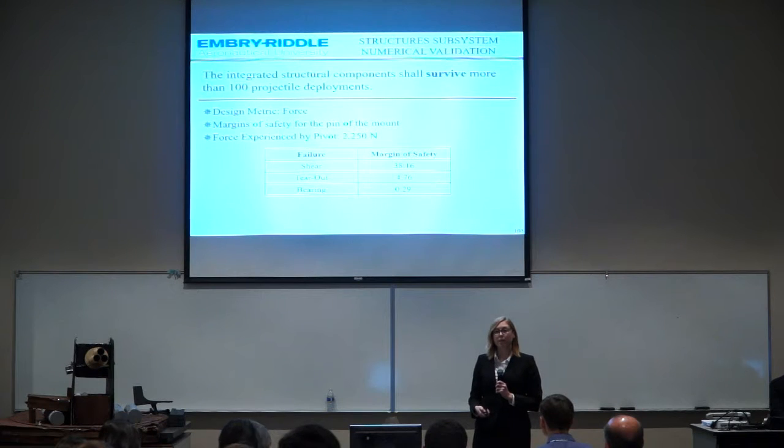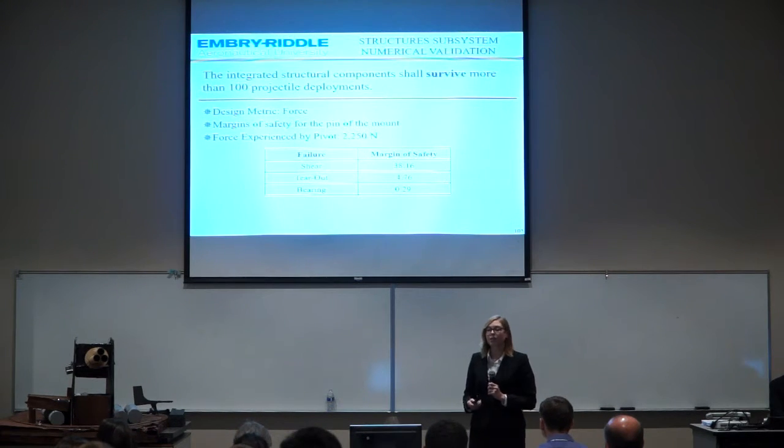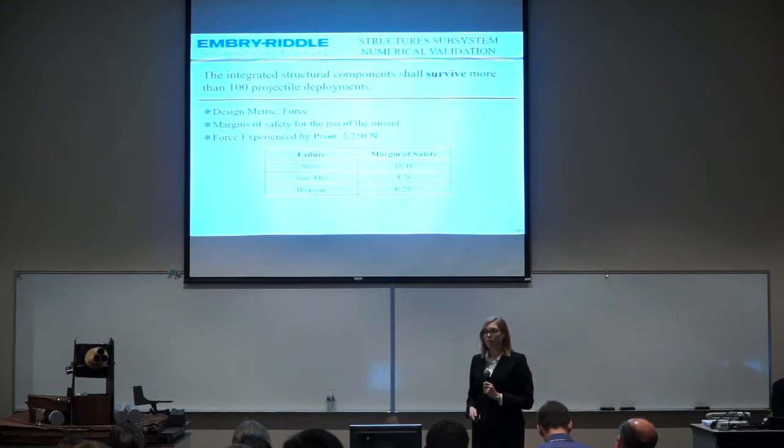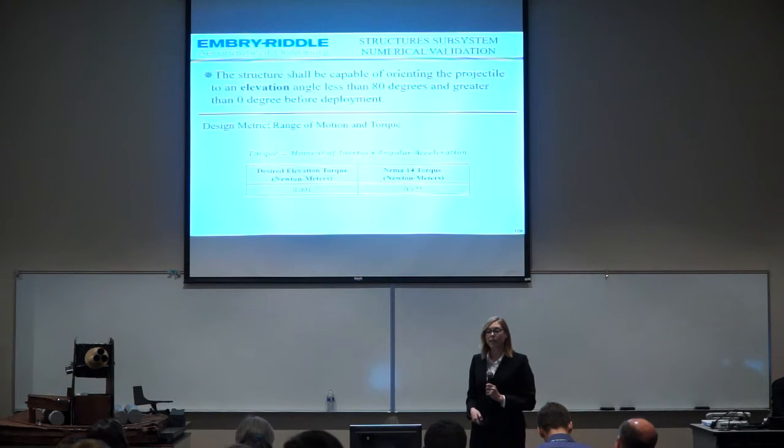Next, we looked at the pin that connects the mount to the barrels. The max force that will be on this pin at any given time is 2,250 newtons. We looked at 3 different modes of failure for this pin: shear, tear out, and bearing. All gave positive margins of safety, therefore the pin will not break and the hole holding the pin will not deform.